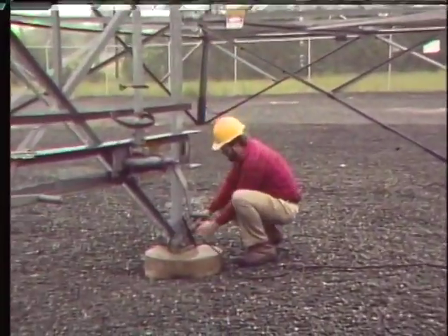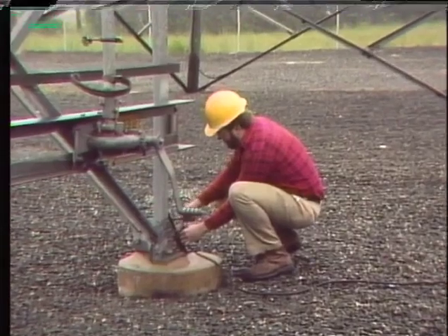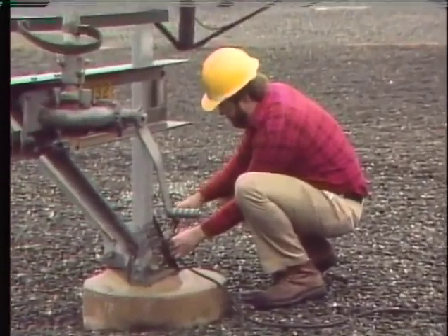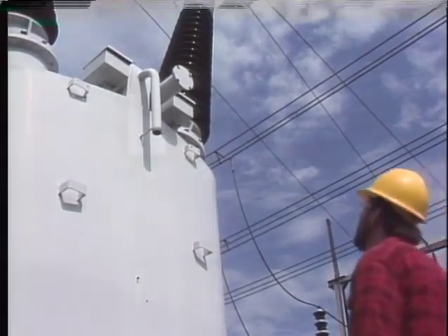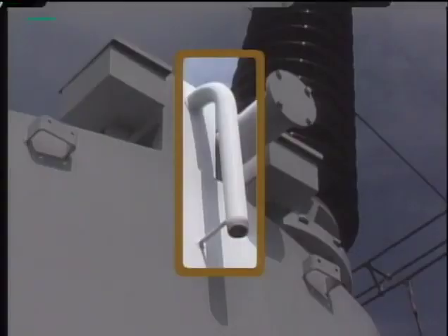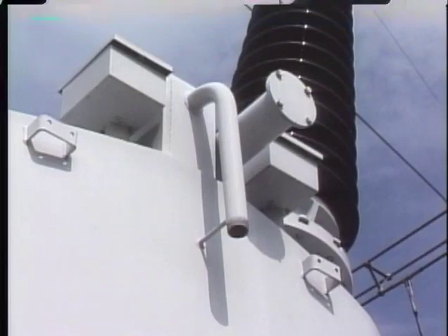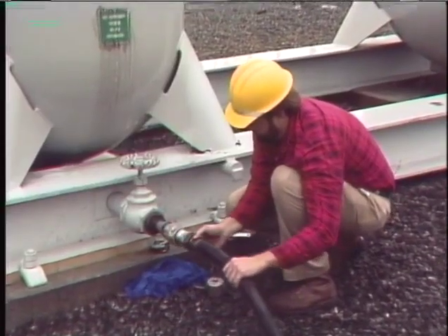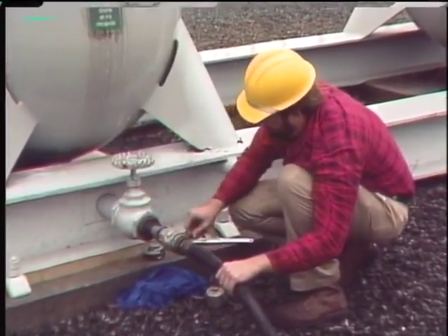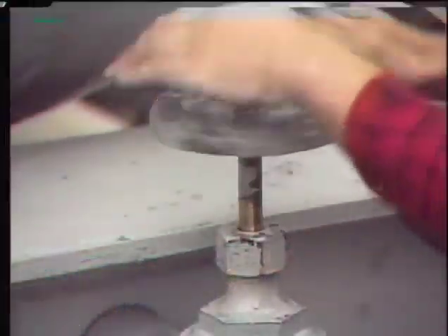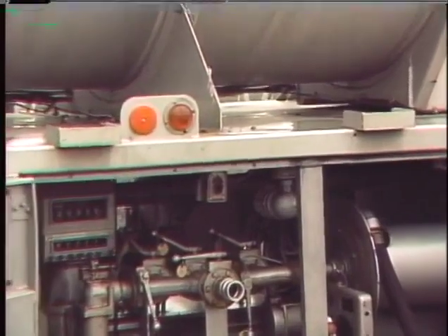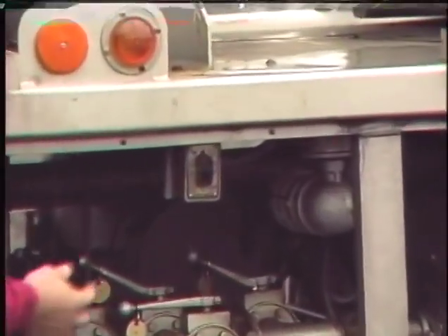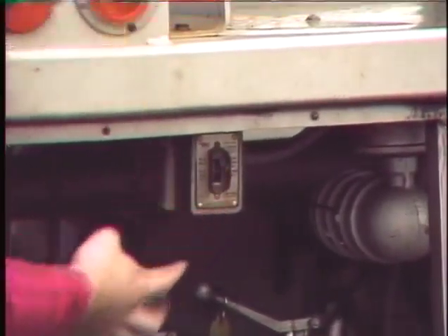The pump and storage tank are grounded to dissipate any static that may be generated when the oil is pumped from the breaker. Vents in the breaker are checked for obstructions that may prevent air from entering the breaker as the oil is pumped out. A hose is connected from the pump to a drain valve at the base of the breaker, and the valve is opened. Finally, the pump is turned on and the oil is pumped out of the breaker tank, through the filters, and into the storage tank.